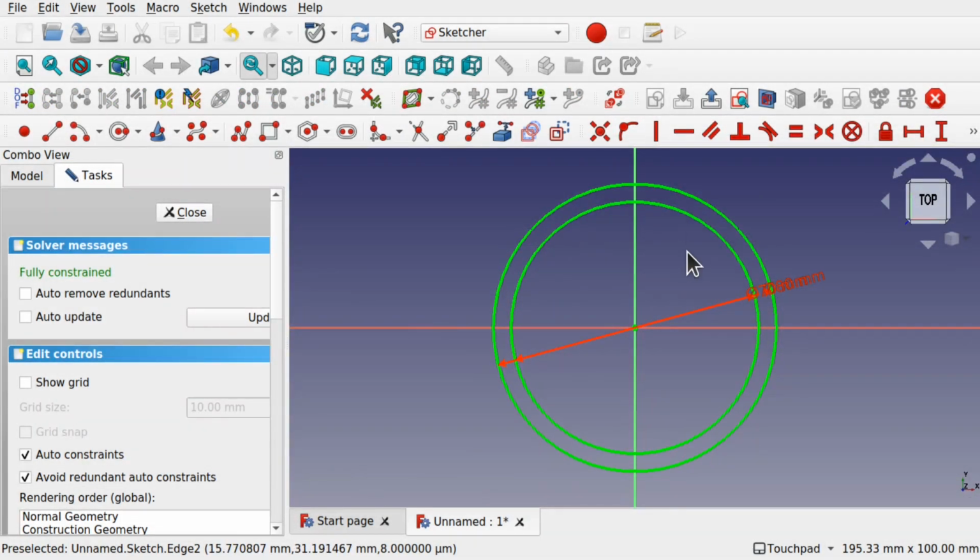So if I extruded this, it will just be a ring, or if I created another one of these and lofted through, all the same size, then we'll get the barrel shape. But we don't want that. What we want to do is create the individual panels of the barrel. So for that, I'm going to need some construction geometry. So I'm going to create a line from this point up to this point and make sure it connects to this outer ring. And we're going to do the same in here, from this point and come out to the outer ring.